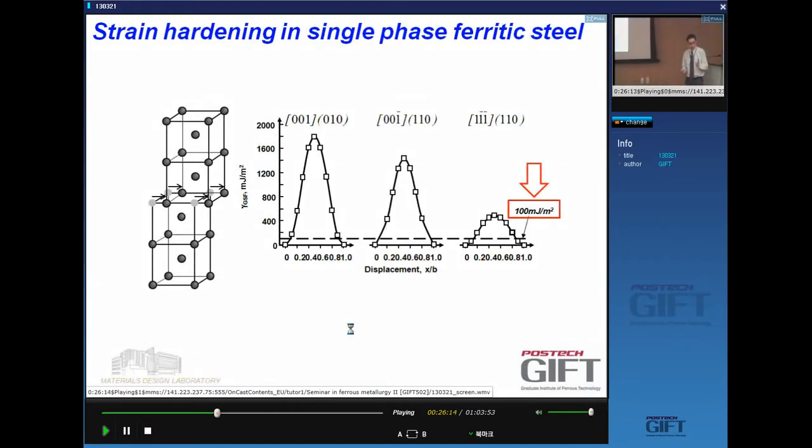What is very important about these dislocations in BCC is they have gigantic stacking fault energies. So these stacking fault energies are so high that we have to use DFT to know what they are. And DFT can help us because you even get the generalized stacking fault energy. So for instance, if you do a shift such as the one I'm showing here in the picture, and you can track the change in energy, and the top here is what we would call the stacking fault energy. The value is thousands of millijoules per square meter, yes?